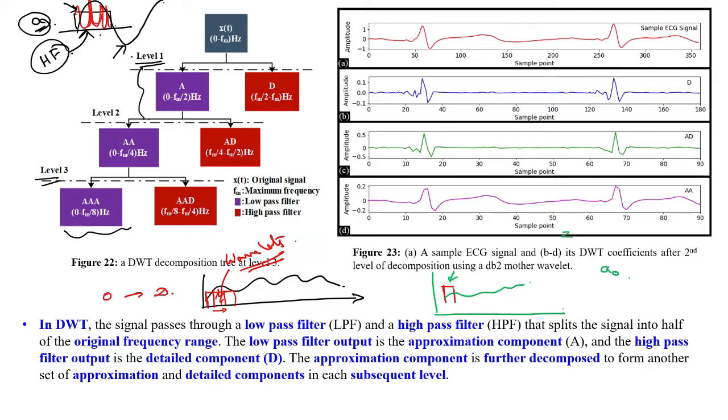Now you move this point to the next level. Again you do it, and you will get a correlation point. When you are moving this filter, it is called translation. Doing this, you will go from 0 to infinity. You will start from time 0 and it will go to infinity. So this is the smallest scaled wavelet you have taken.